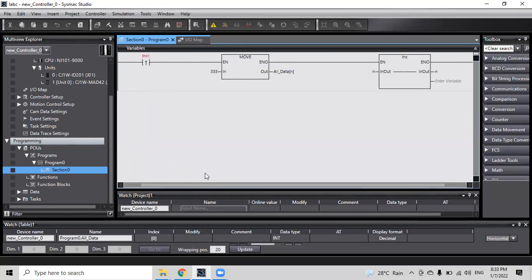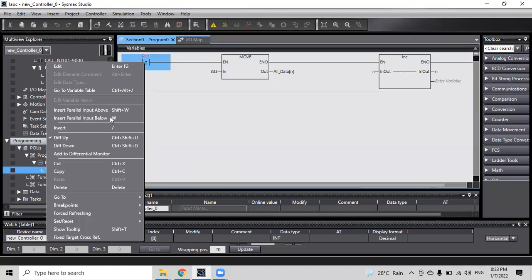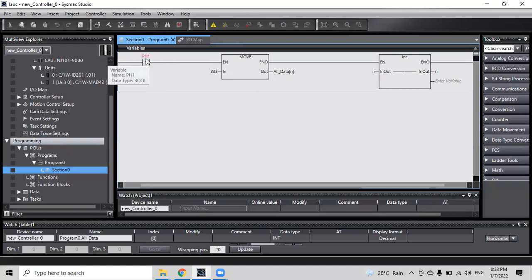So once we finish this step, the next step is to create the ladder diagram. All right. So the first component is the input again. We just type C. We can have this one and right click to select the up arrow, which is rising edge. All right, and rename this one as PH1. Capital letter, please. PH1. Okay.